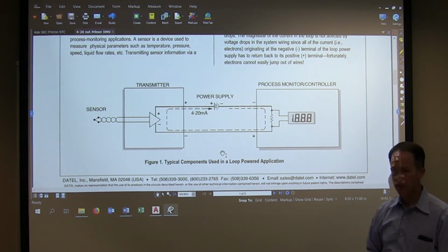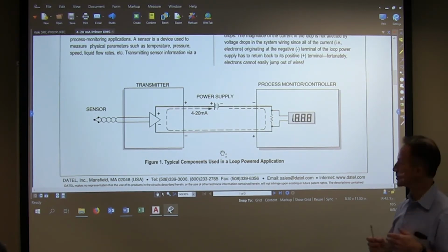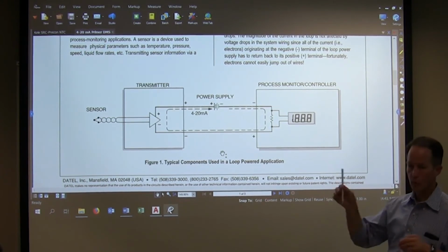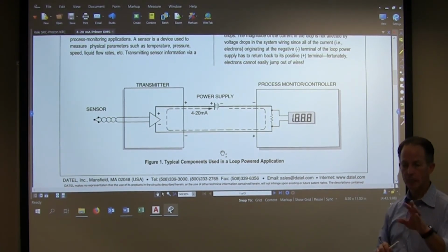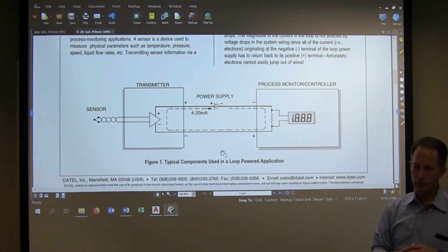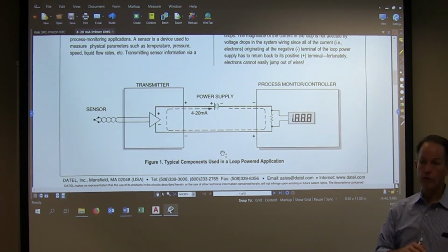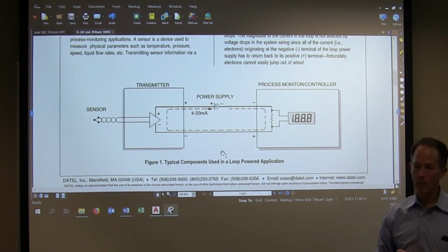What else? So what would we see? You said browning out. What are some symptoms of that? Okay, so say for instance, your sensor, whatever it is, say it's a pressure sensor, and it's supposed to do pressure from, say, 0 to 5 inches, say 0 to 2, so we don't blow anything up. And you know you're over 2 inches on this particular sensor. You've got a gauge on the side, a magnehelic or something, that says you're above 2.